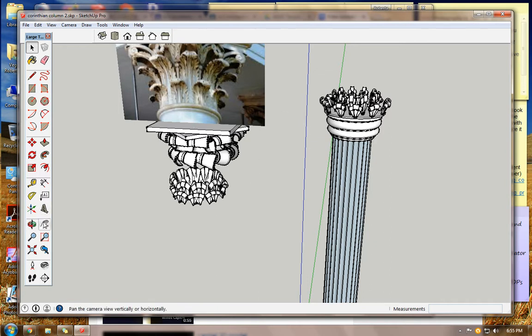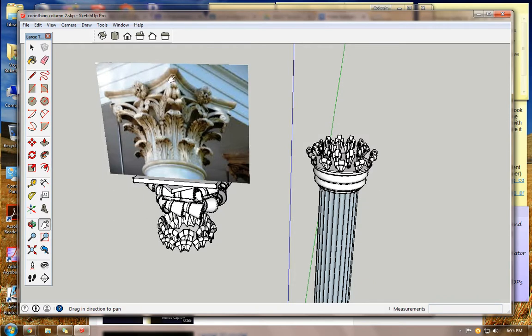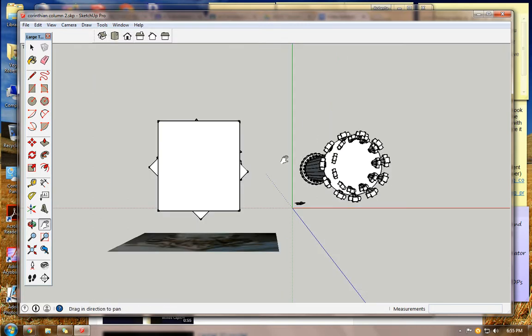I need to add these flat spaces above that support the upper elements of the roof. So I'm going to go to top view, and I want to draw a rectangle, and my rectangle should be on top of my pieces here. So I'm just trying to catch an angle where it will draw any size rectangle at all up near the top.